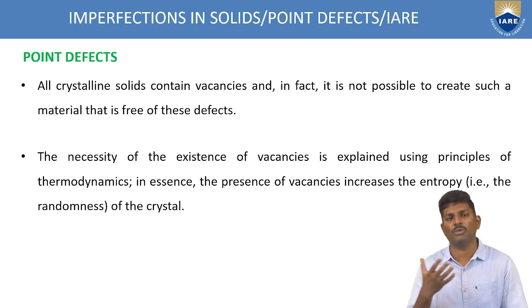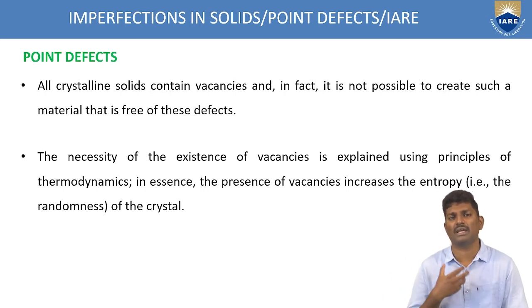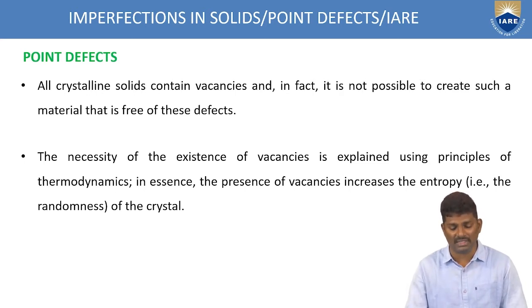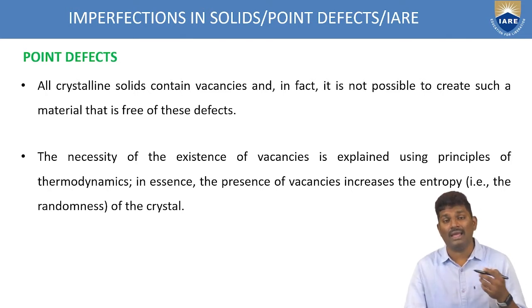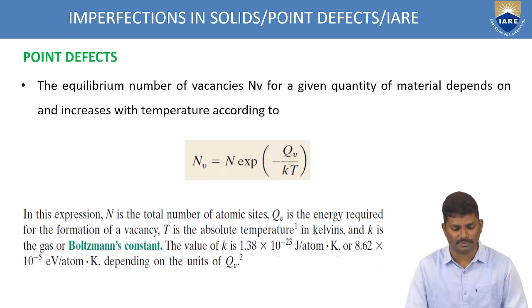Because of this movement of the atoms, some defects occur inside the atomic structure. So generally, it is not possible to create any material free from these defects. The necessity of the existence of these vacancies is explained by the principle of thermodynamics, and vacancies increase the entropy of the crystal.